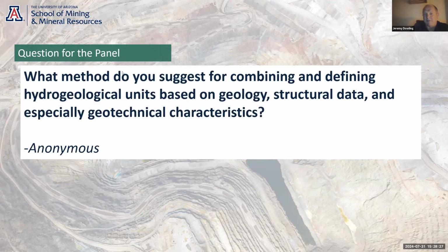So every site is different, and you have to look for the information and interpret it with the hydrogeologic information. But it's almost always the case that the geotechnical data and characterization and the hydro data sets can be mutually enhancing, and they should be used in combination to develop the conceptual models for the site, both the rock mass model, the structural model, and the hydrogeological model.